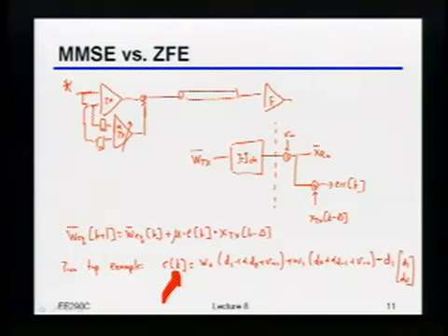So the major difference is basically the equalizer itself doesn't see any noise. So that makes it a ZFE. Yeah, so you're saying the difference here is that the equalizer itself doesn't see any noise. It's really more that, unless I do something funky, I really don't have the analog input into the equalizer, which includes the noise. All I really get is the analog output of the equalizer with noise. So that's really the main distinction.